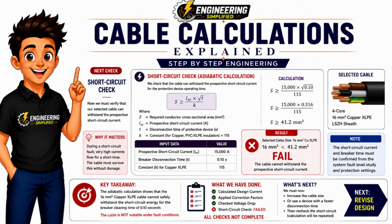Now we need to carry out one of the most important checks in any cable calculation, the short-circuit check. Although our 16 square millimeter cable has already passed the current carrying capacity and voltage drop calculations, it must also be able to survive a short-circuit fault. During a fault, thousands of amps can flow for a very short period before the protective device disconnects the supply. To verify the cable can withstand this energy, we use the adiabatic equation.